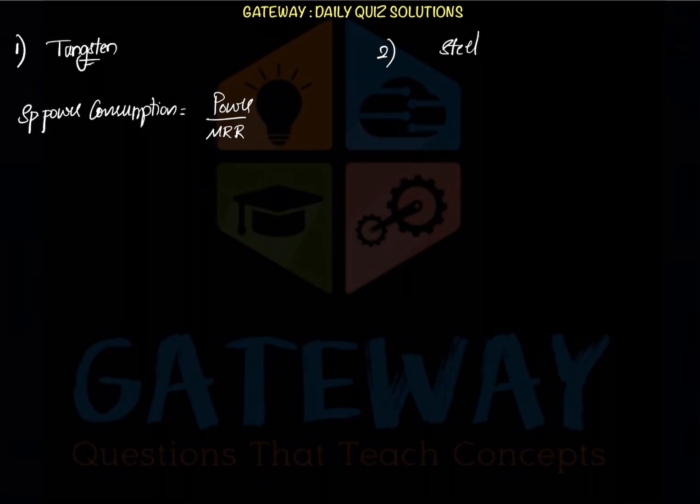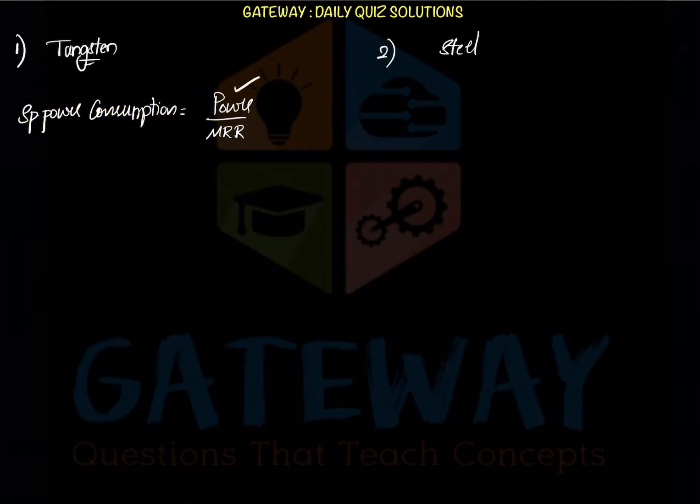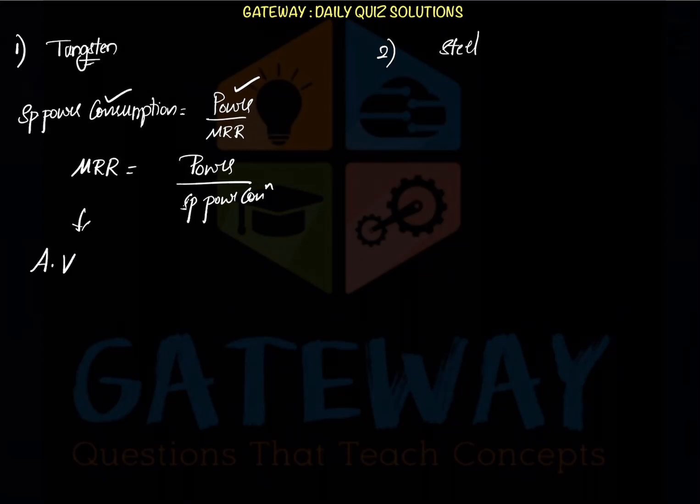Here in our question, the specific power consumption was given as 12 watt minute per mm cube, and the power used for the electron beam is also given, 5 kilowatts. So the power is known and the specific power consumption is known. From that we can write the MRR. MRR is equal to power upon specific power consumption, right? And MRR we can generally write as volume flow rate, which is area into velocity.